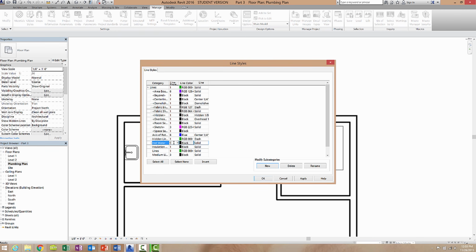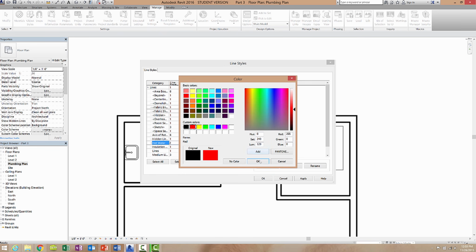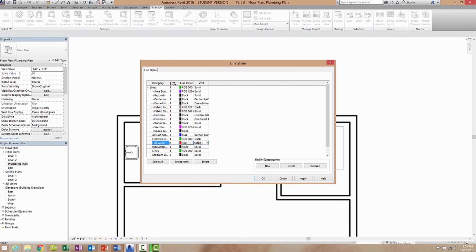This is going to have a line thickness of 2. It is going to be a red line, so I'm going to click red right next to it, and hot water is usually represented with like a dash followed by 2 dots. So I'm going to search for like dash dot dot. Here we go, dash dot dot, and I'm going to click on that.